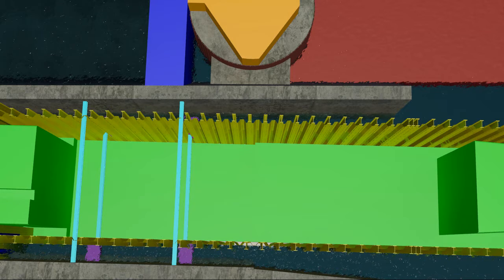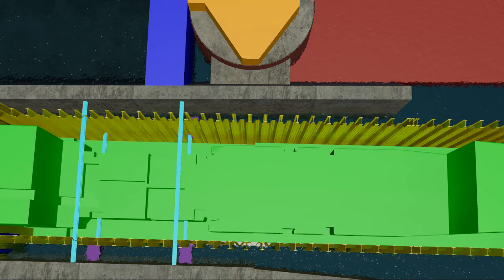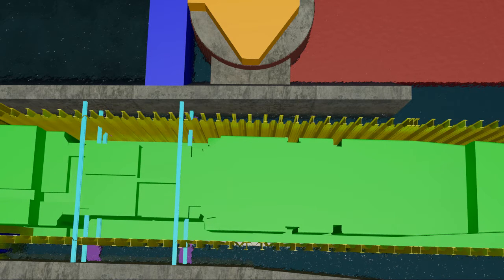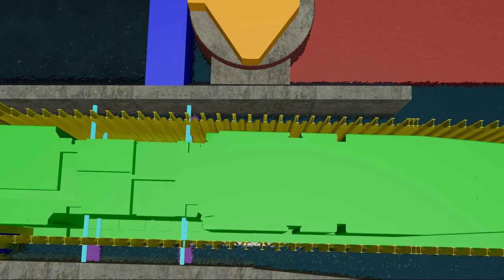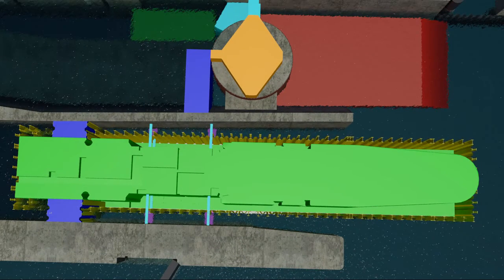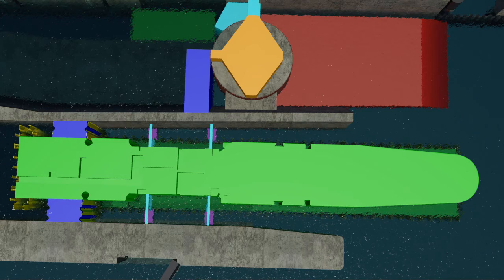At this point, we are able to place the remaining monolith walls M23 through M26. During this process, we also install replacement struts, remove the upper stabilization struts, and finish placing the wall. To complete the wall installation, we cut and remove the coffer box to top of tremie elevation with the future M21 coffer box seal to remain.